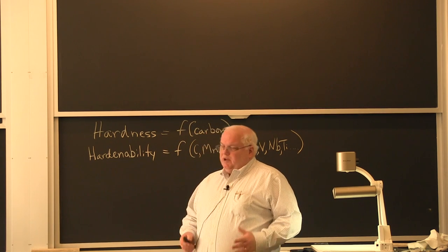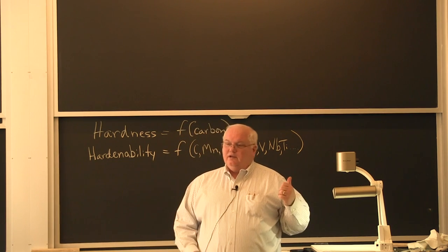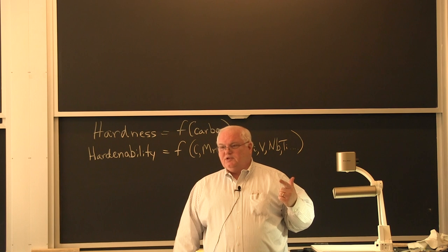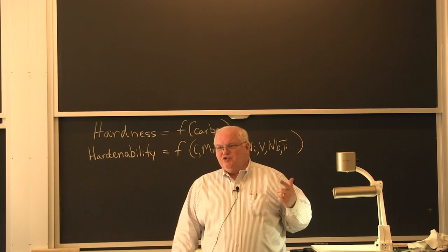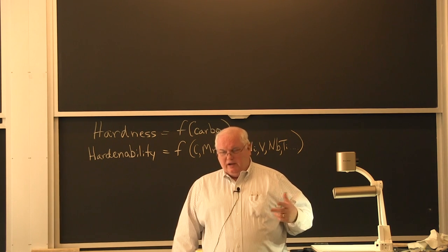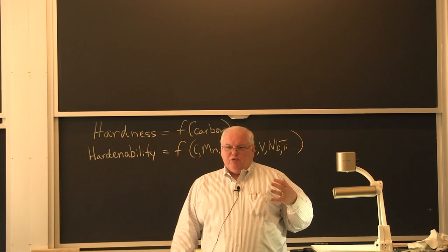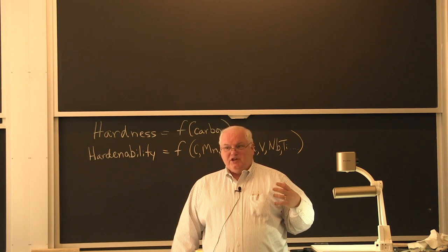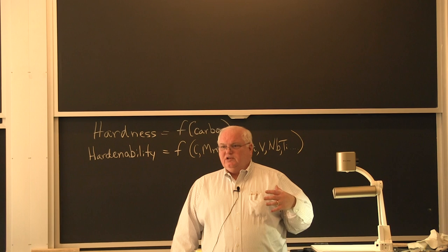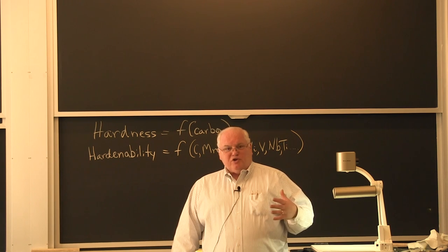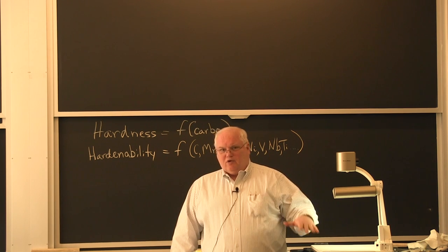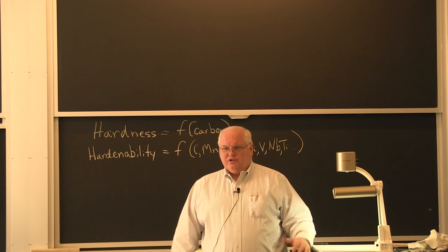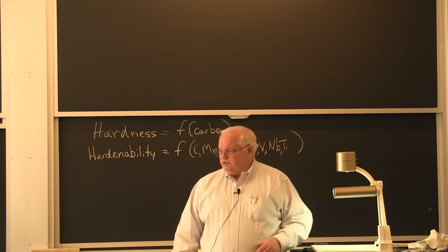Hydrogen cracking has many names. It can be called hydrogen cracking. Sometimes people confuse hydrogen embrittlement with hydrogen cracking. Hydrogen embrittlement is the fact that hydrogen in the steel can cause the steel to act in a brittle manner. Hydrogen cracking is the actual production of a crack, due to the hydrogen embrittlement and an applied stress.